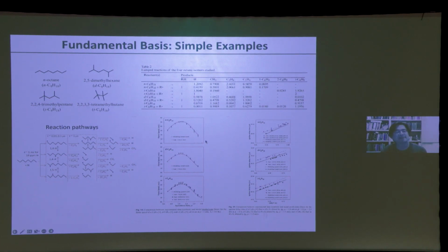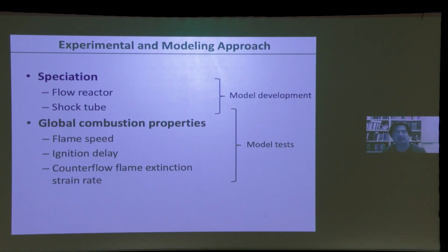For those who are interested in this problem, you can read some of those papers, which I'll give you the list of at the end. The key point is, by throwing away perhaps thousands of reactions, just to write it simply, I have, for example, the fuel dissociating into hydrogen, methyl, ethylene, and so on. And each of these values is basically what I showed you earlier, related to alpha, beta, gamma, the Greek letters. And then you have a secondary reaction with a series of radicals, with their stoichiometric coefficients simply derived from the detailed model. Okay, but now from the fuel all the way to the small species are described by essentially 2 long reaction steps. You can reproduce flame speed extremely well, and you can reproduce ignition delay time without tuning anything. Right, so that shows that many of these detailed models, so many reactions, are completely unnecessary. They are doing nothing more than to conserve mass through a long list of chemical reactions.